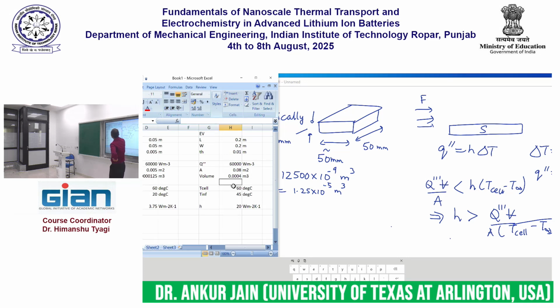Moreover, the amount of current requirement for a cell phone is very small compared to the current requirement for an electric car. So if, let's say, the current output required out of this cell is 10 times that in an electric car compared to a cell phone, then this must go up by 100 times, because the heat generation is I square R, right? So let me just add a couple more zeros here. And now the problem is out of my hand, right?